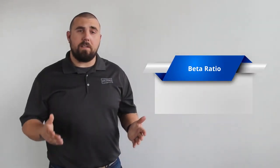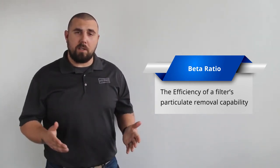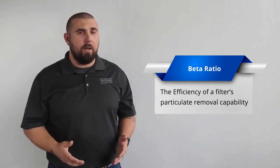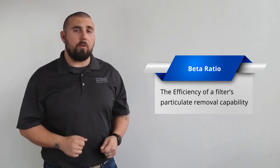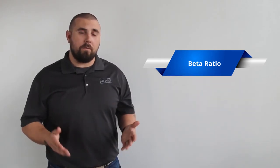Beta ratio is defined as the efficiency of a filter's particulate removal capability. That efficiency is expressed as the filtration ratio, or beta, which is the relationship between the number of particles greater than or equal to a specific size of micron, counted before and after the filter during testing.